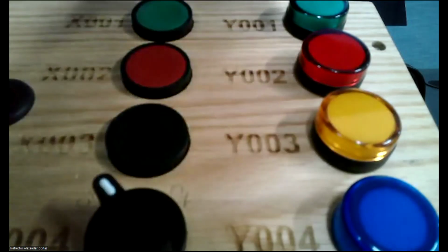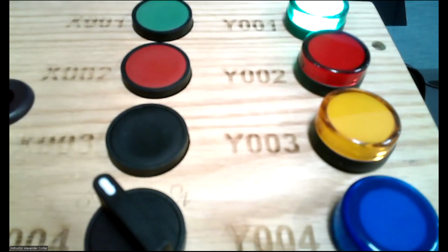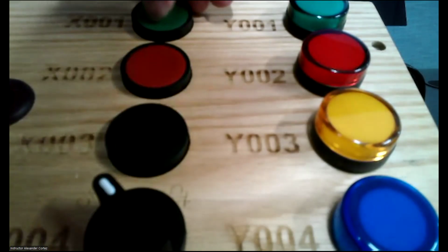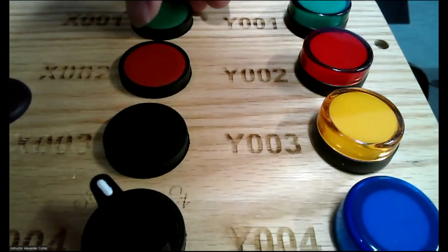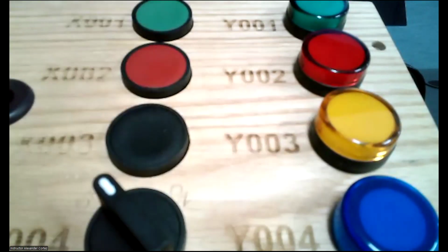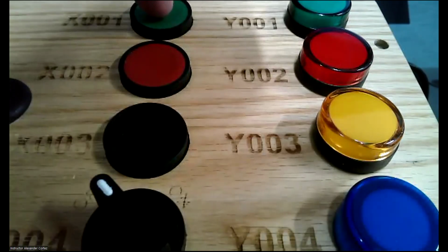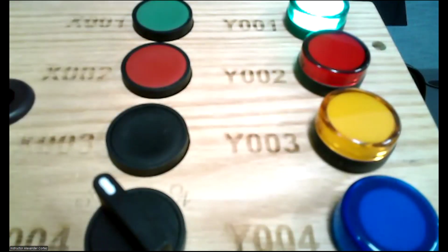Now we're going to operate, right? And remember that we just hold it, right? That held, and I'm going to explain why that happened. So on this one, we don't have to hold it, right? Because this is an off delay. So as soon as we press and we get a pulse of continuity to the off delay, it's going to delay turning off for 3 seconds. That's what the off delay is, right? So we're going to do it again. 1, 2, 3, off.